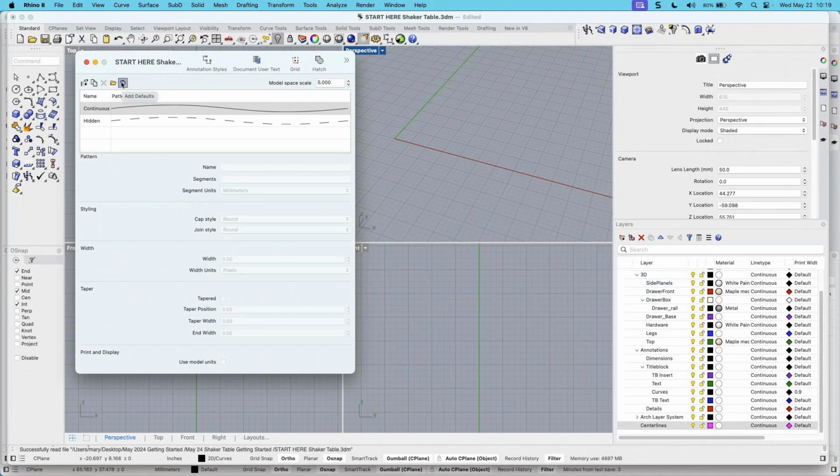That will go through and delete all of your unused named objects, layers, line type styles, annotation styles, textures. You get a choice of what to purge. So I did it the easy way. I used purge, but then I wiped out all the default line types that I wasn't using. It's a really good way to make sure you're handing off a clean file.